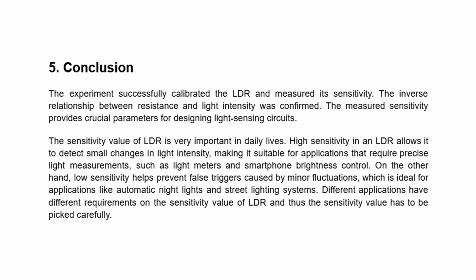And next, for the conclusion, the experiment successfully calibrated the LDR and measured its sensitivity. The inverse relationship between resistance and light intensity was confirmed. The measured sensitivity provides crucial parameters for designing light sensing circuits. The sensitivity value of the LDR is very important in our daily lives.